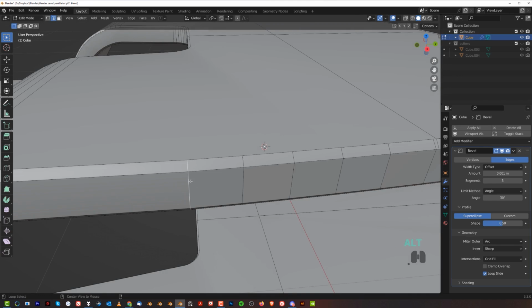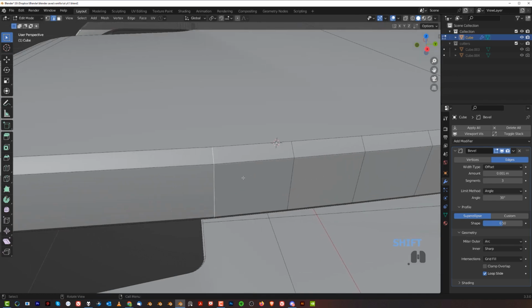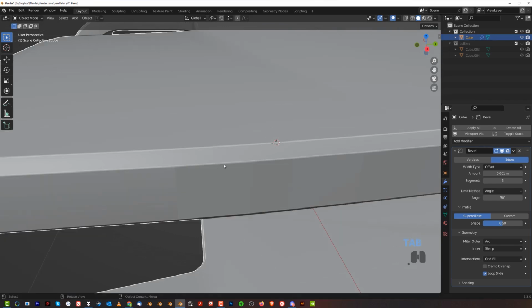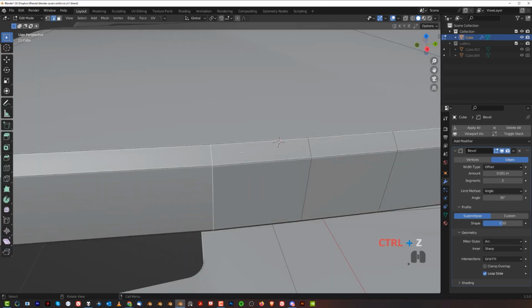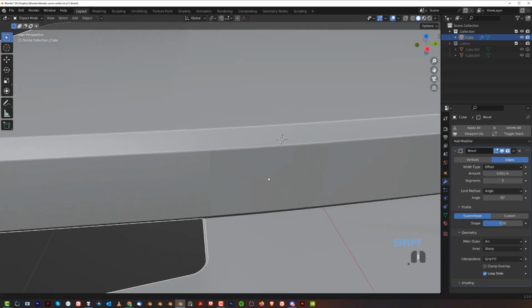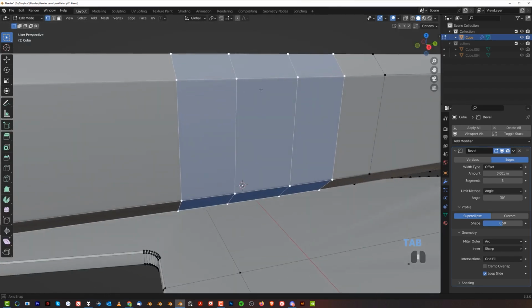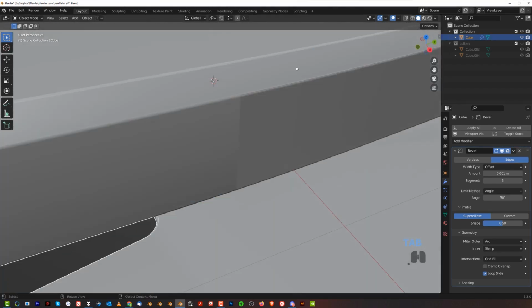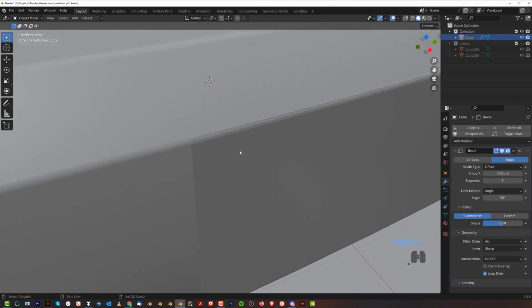Nope, that's actually a problem with this edge. So let's Control B that to split it, to introduce a little bit more diversity here. That didn't fix the issue. Let's just create 1 more or 2 more edges in here like this to ease off this transition. It still doesn't really work very well. Press 3 to clean it. Something is not right in here.